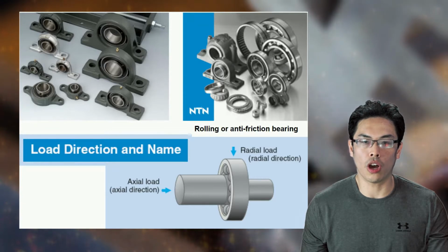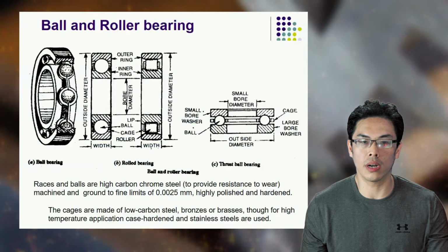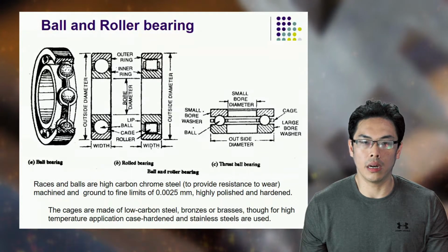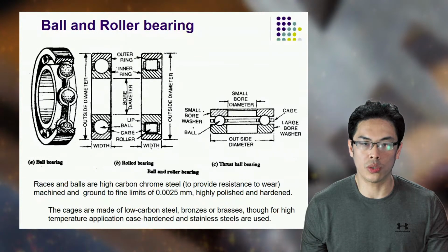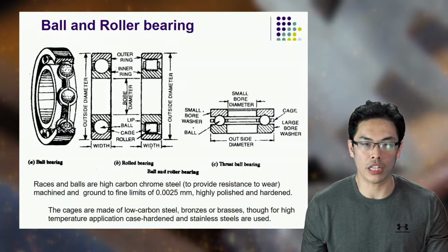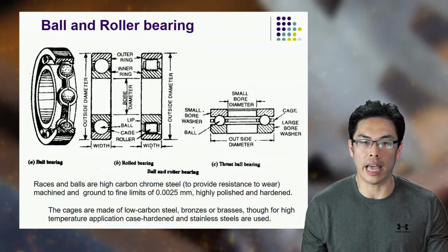Owing to the low starting torque, a low power motor can be used for a line shaft running in ball bearing. Types of roll bearing. Single row deep groove ball bearing, incorporating a deep hardened raceway, which makes them suitable for radial and axial loads in either direction, provided the radial loads are greater than the axial loads.